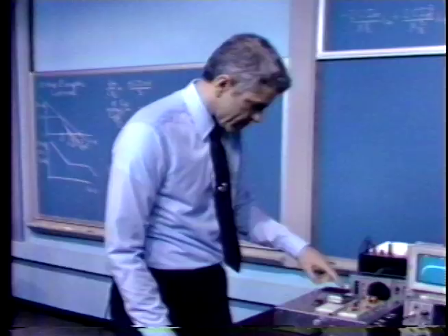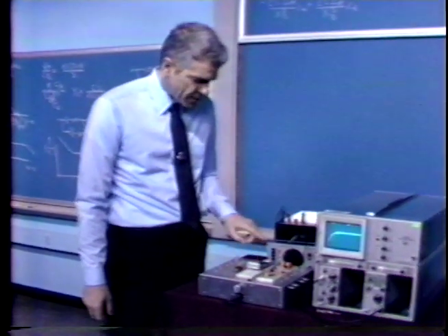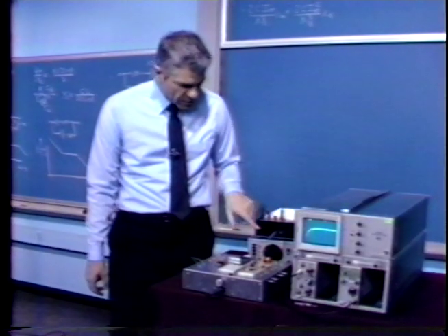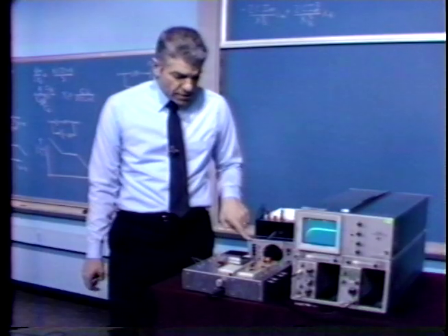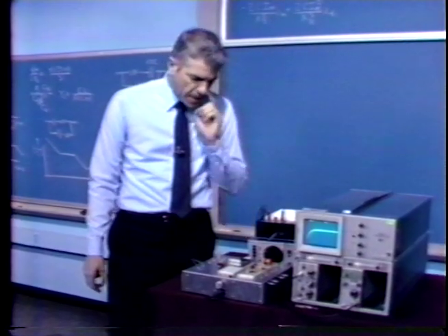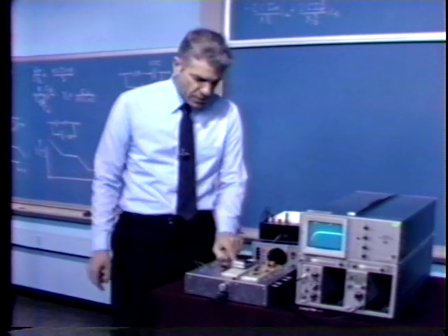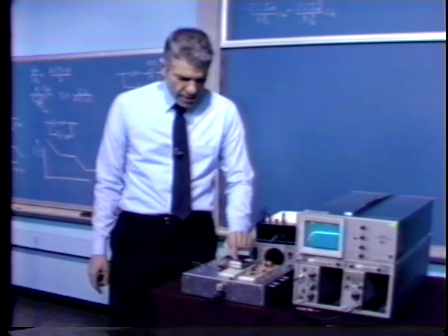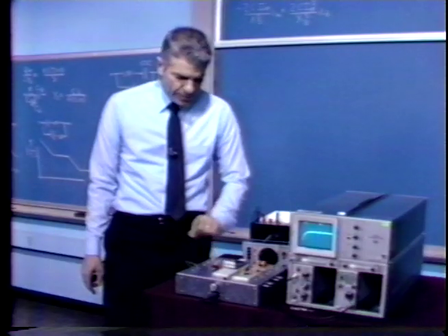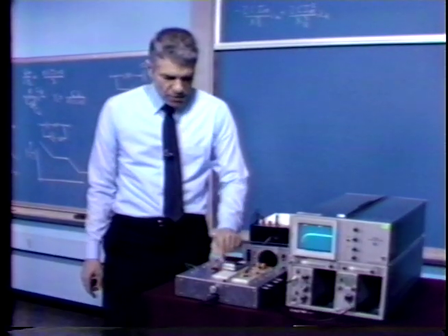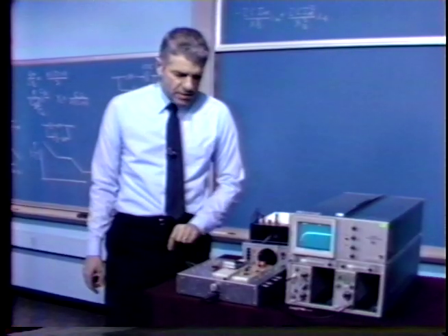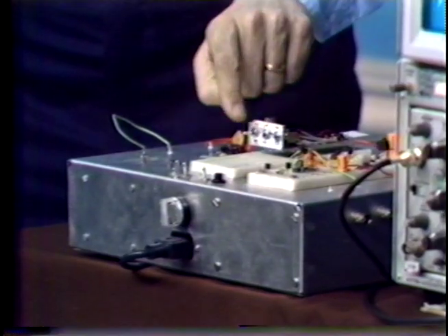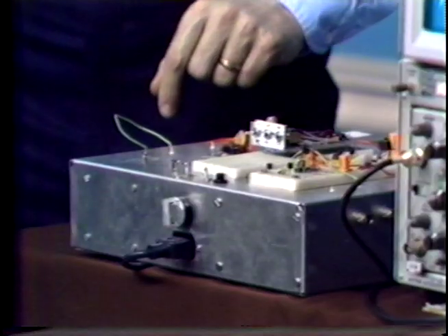Here we have our experimental setup. This is a little bit different from the past one. What I have, once again, is the power supply powering everything, a generator that lets us put steps into our circuit. We've changed the board in this case. Here's the circuit itself. We have the 301A or the 101A type amplifier and its buffer amplifier, and a series of switches on the front that first of all let us select from various types of compensation, also let us select the R1, C1 product. So that's what these three switches do.